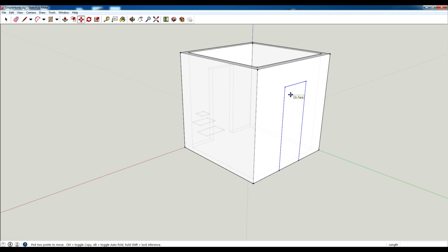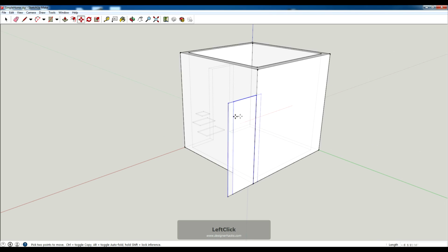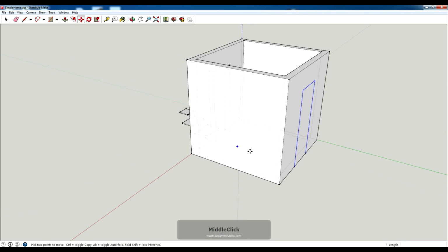And what happens if you start to manipulate this, you're going to have some issues because I want this door over here. I hit Q, which is the quick command for rotate. That's also this tool here. You can see it's kind of finicky. This always sort of happens. Like, I want to rotate this along this axis. However, you can see it's switching between the three depending on which way I am at. But you can use the arrow keys for this. It helps.